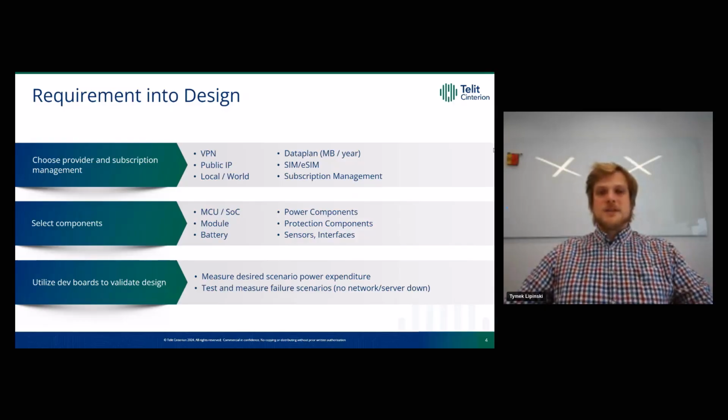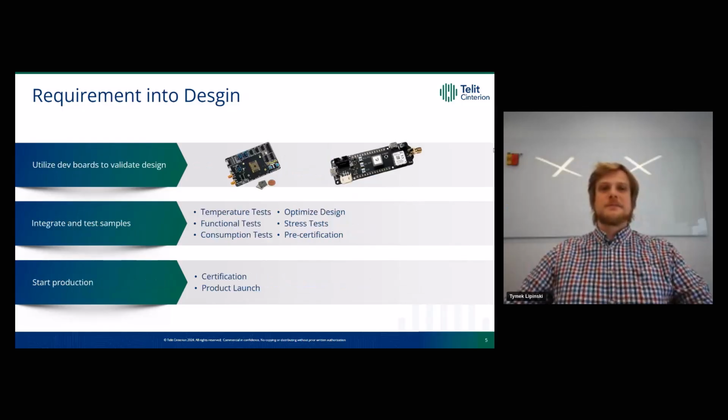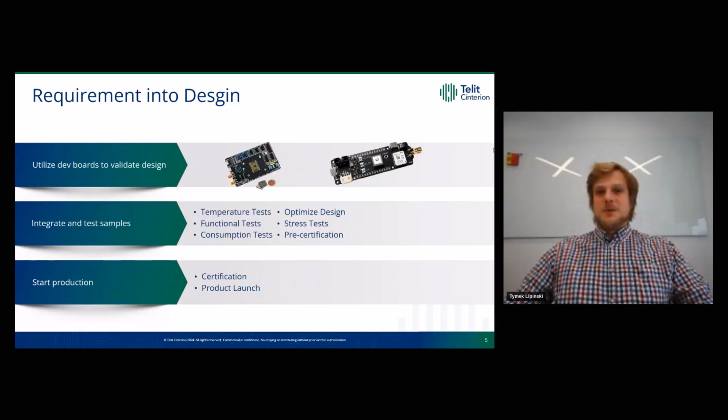We also have to test and measure failure scenarios. So there is no network, poor coverage, server is down, the modem could not register to the network, it rejected us for whatever reason. That also has to be covered and taken into account. Dev board, right, a variety of selection and options to choose from to tailor down to your design.